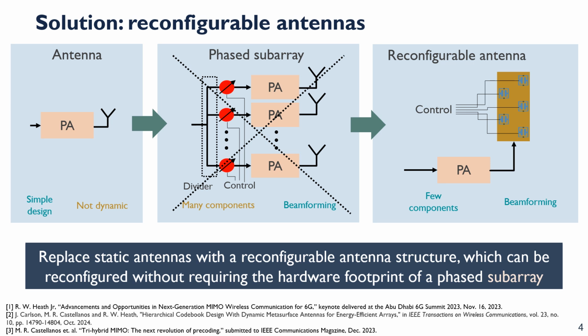Rather than this, we're looking towards the reconfigurable antenna architecture, where rather than controlling and doing beamforming with phase shifters, we have these reconfigurable low power components that are integrated onto each of the different antenna elements, such that we can have low power and a simple design with fewer components as we scale up the number of antennas in our antenna array.